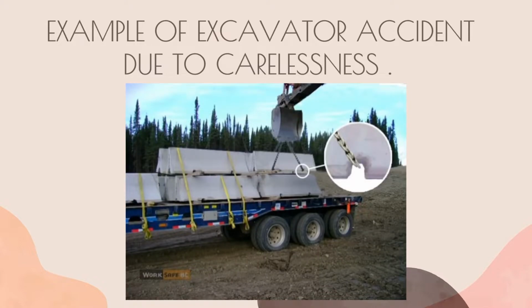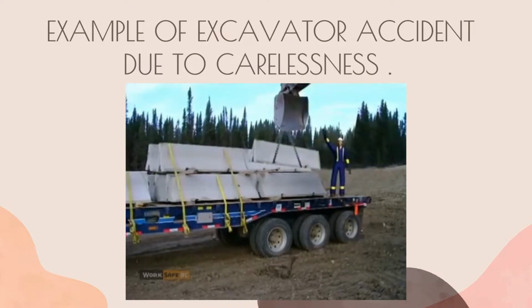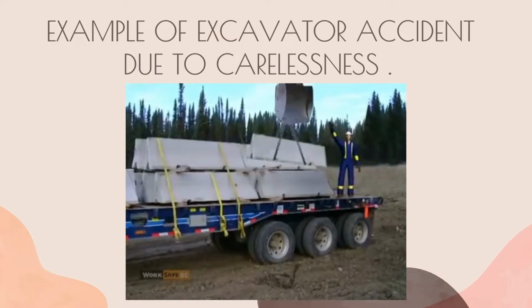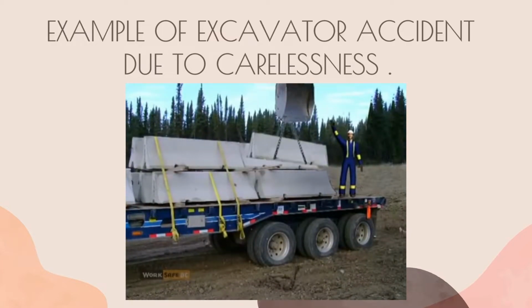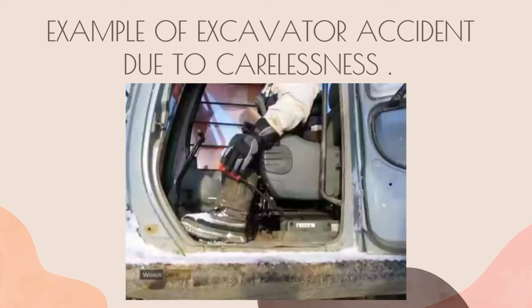The truck driver had some tie-down chains, so he rigged them above the excavator bucket and around the two grooves beneath the barrier. When the excavator lifted the barrier, one chain slipped out of its groove. The truck driver waved to the excavator operator to stop and to lower the load so he could reposition the chains. The operator couldn't hear what the driver was saying, so with the load suspended, he engaged the safety lockout lever. This disabled the operating controls, preventing the excavator and boom from moving.